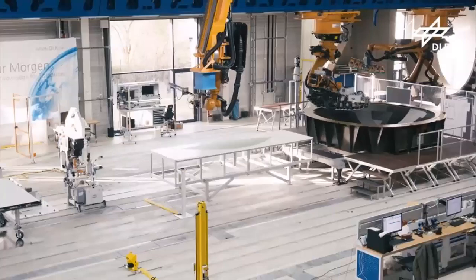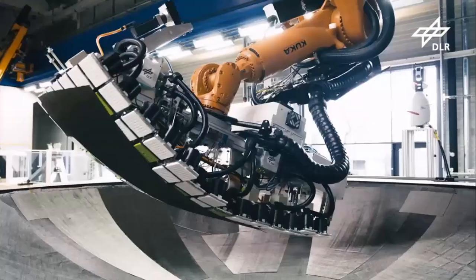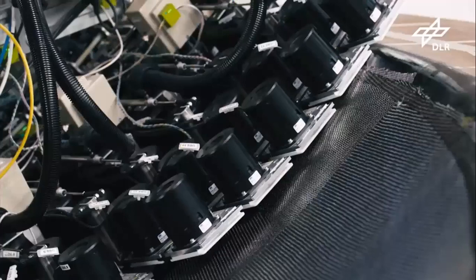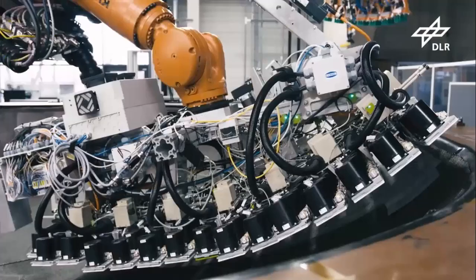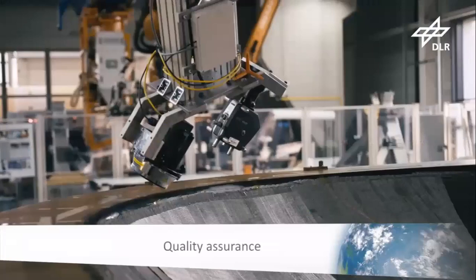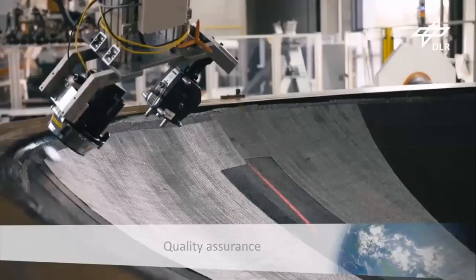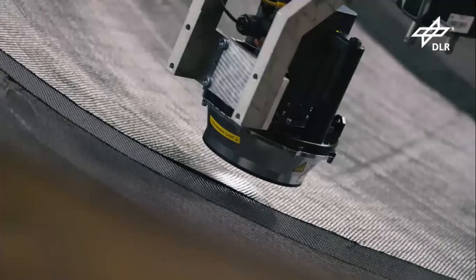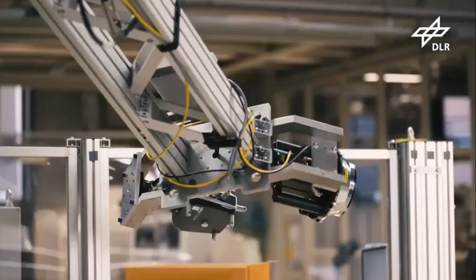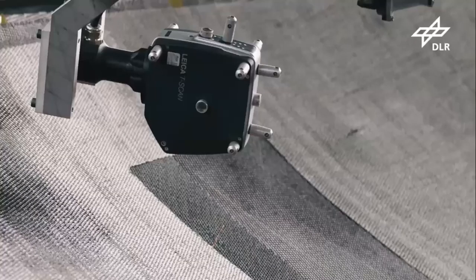Optical sensors within the modules monitor the quality of the draping process. Finally, the cut piece is placed in the target position. The quality of every applied cut piece is verified. For the inspection of the draping quality, a fiber angle camera is used. For the exact detection of the edges of the cut piece, a laser sensor with external positioning is used.